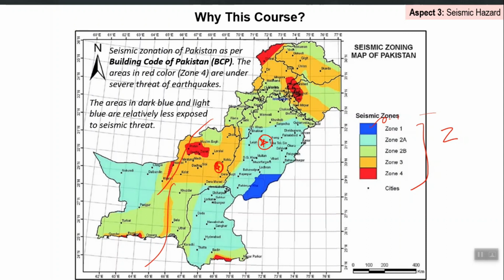So, the question was about site specific hazard assessment, and I was emphasizing its need. Currently, what is happening in our local context is that there are several very important structures which deserve this study, site specific PSHA, but designers are using code numbers and relying on those, right. Sometimes the code number is high, and site specific PSHA tells that the actual level of seismicity may be less than that, and sometimes the code's number is low and the site specific hazard reveals that the actual level of hazard is more. This mostly happens in the vicinity of active crustal faults.